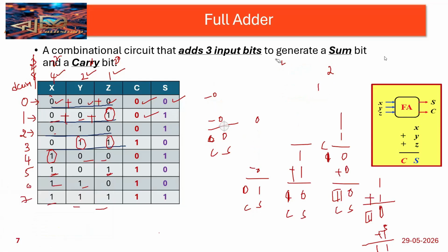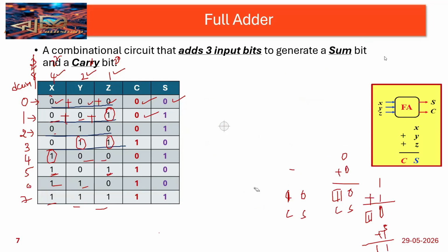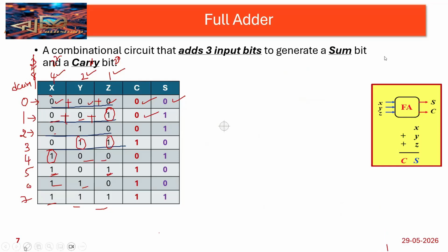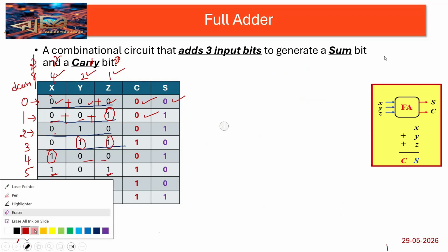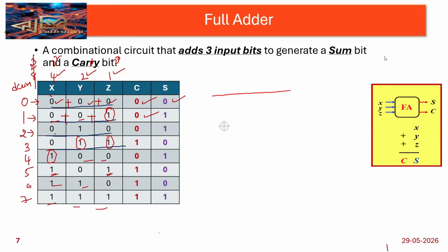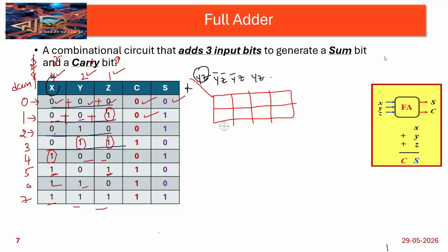Then you need to again design the K map, or calculate the Boolean equations from the K map. Now here three variables we got, right? So three variables, how many combinations? Eight, right? Then we will write a three variable K map. On the right side, the most significant bit is X, and then yz we can write here. Two variables give four combinations: y bar z bar, y bar z, yz, and yz bar.